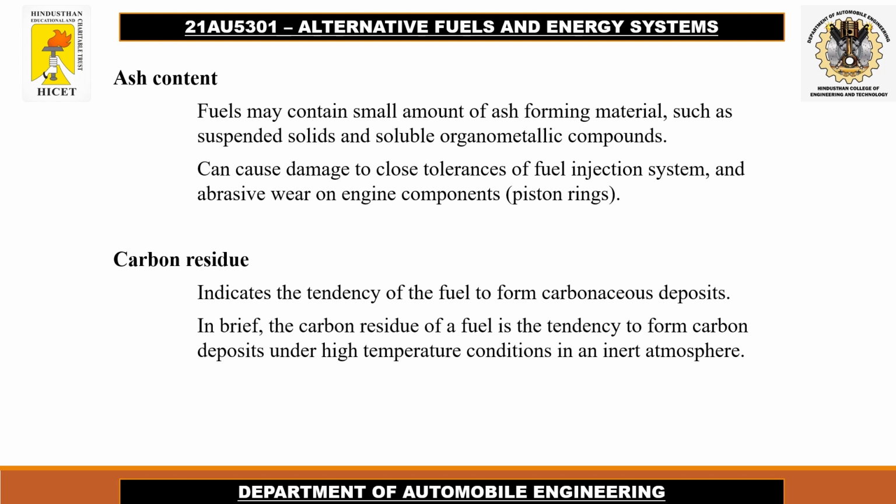And ash content. Fuels may contain small amounts of ash forming materials such as suspended solids and soluble organometallic components. These can cause damage to the close tolerances of fuel injection and abrasive wear on engine components such as piston rings and cylinder walls. And finally, carbon residue, that indicates the tendency of a fuel to form carbonaceous deposits. In brief, the carbon residue of a fuel is the tendency to form carbon deposits under high temperature conditions in an inert atmosphere.